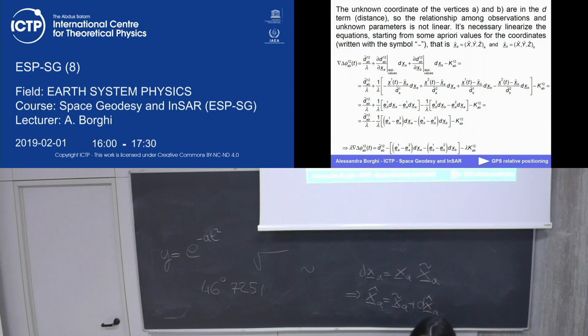and after, for instance, you correct the data for the clock biases, so you have improved your solution. After you correct the data for the cycle slips, so you have improved your solution using triple differences. After you fix the ambiguity, so you improve the coordinates. After the last run, when you want to estimate, you have improved all these quantities, and you try to arrive at the correct solution, correct in terms of the precision that you fix.